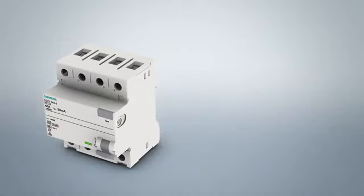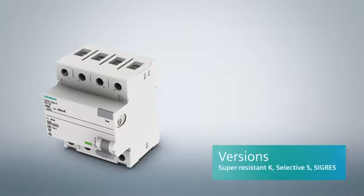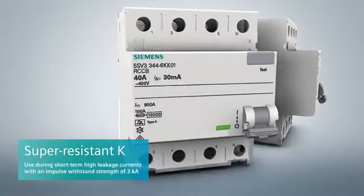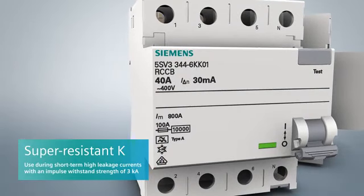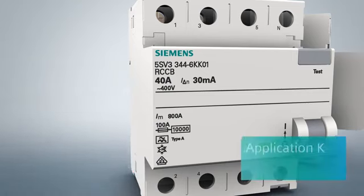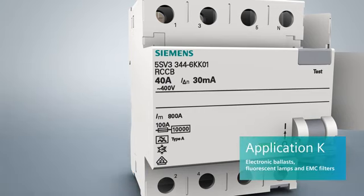Besides the type differentiation of residual current protective devices, they are also available in different versions. The super-resistant version is employed when no disconnection of the consumer is required and desired in case of short-term high-leakage currents. Super-resistant residual current protective devices offer high surge current withstand capability of 3 kA. Typical applications include electronic ballasts in fluorescent lamps and EMC filters.